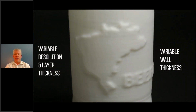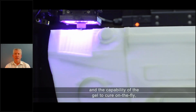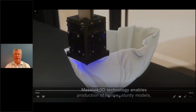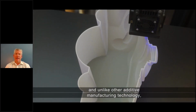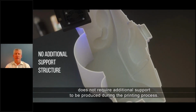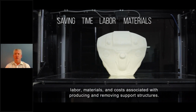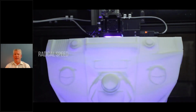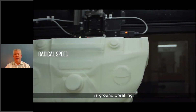Using some advanced software, you can actually vary the wall thickness and vary the layer resolution. You see here that on the fly, we're able to produce these parts very, very quickly. Now our parts are printed hollow. Let's save that material. Let's save that cost. Let's save that time. You'll see that it's a very efficient way to produce parts, samples, and prototypes. There's no additional infill required. There's no additional support structure required. If you need additional strength, you can apply it later, or you can actually design in any sort of ribs or support structure that you might want.